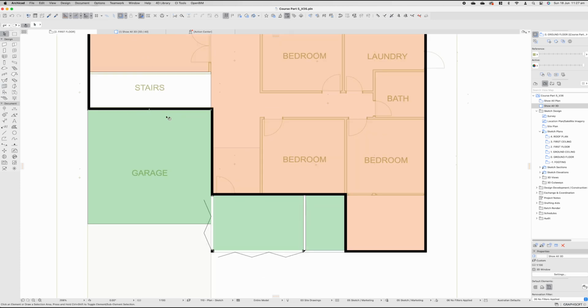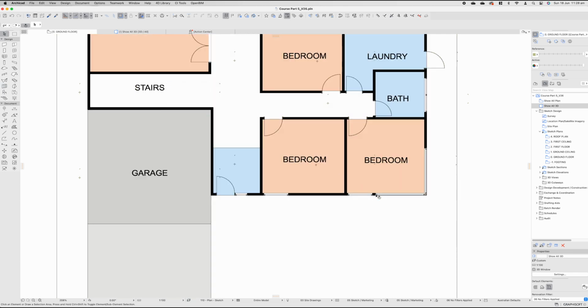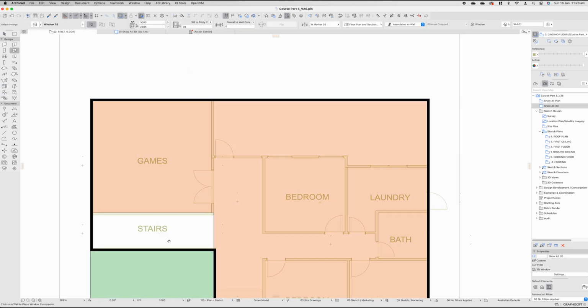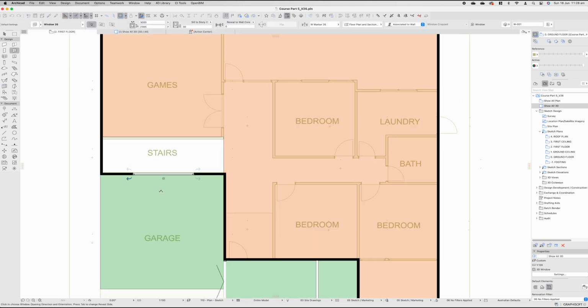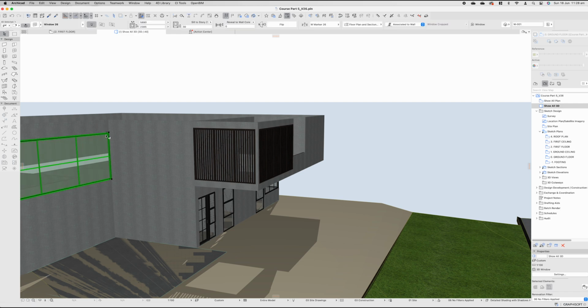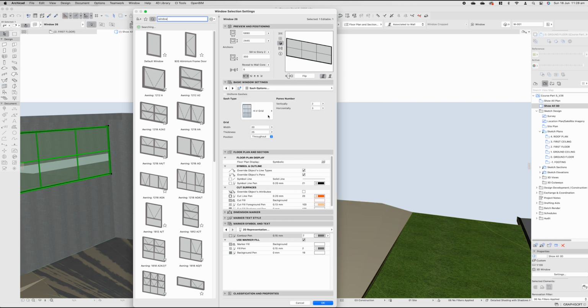On this side of the stairs, we also want to replicate something very similar, but we just want to make that a window. So if we dive back down to our bedroom, grab one of these corner windows, or even let's grab this games room window, come to the stairs, drop that in all the way, adjust it to full length, come into 3D, make sure it is the same height as our bifold doors over here, open up our settings, go to the HV grid, change the number of grids.